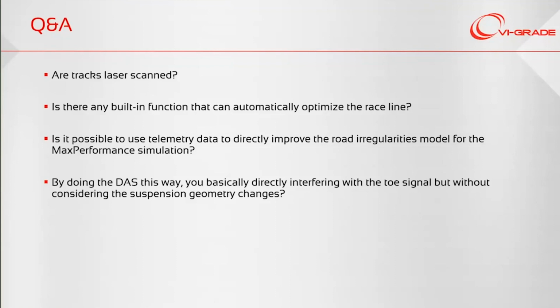Any other information, Francisco? No, I think this is correct. So in general, in VI real time we do represent the suspension geometry as a surface lookup function depending on wheel travel and steering input, for what regards kinematics of the front axle, and this can be modified by using a difference and offset in the signal as Vince has shown in this part of the presentation.